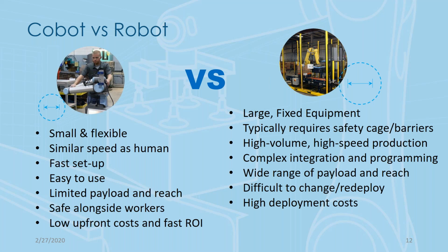When the collaborative robots first came out, they were implemented in some high-speed applications, and they had a lot of failures in the field with bearings and some of the joints. And so they have been continuing to improve the designs and making them more reliable and robust, but they're still really meant for lower speed applications. So that's probably one of the biggest things to consider.